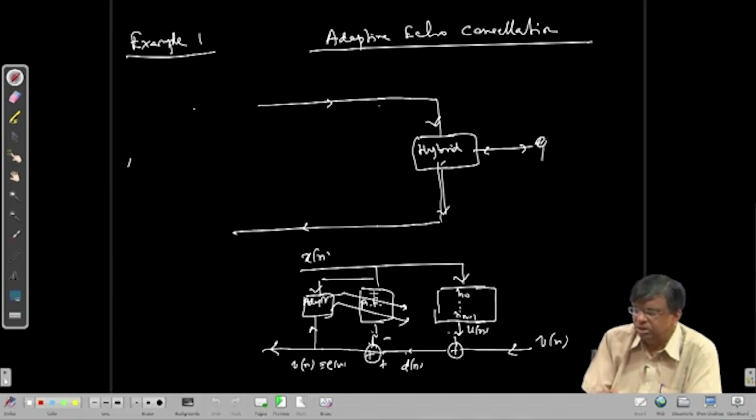So, we make sure that the fluctuation ranges are small by adjusting mu. In fact, it is known that when mu, the step size in the LMS, is made very small, the fluctuation range will be small, and with that we are happy. So, technically it is not an actual optimal filter. It will not be exactly equal to Un, there will be some error, coming from the fact that adaptive filters do not converge absolutely, they converge only in mean.